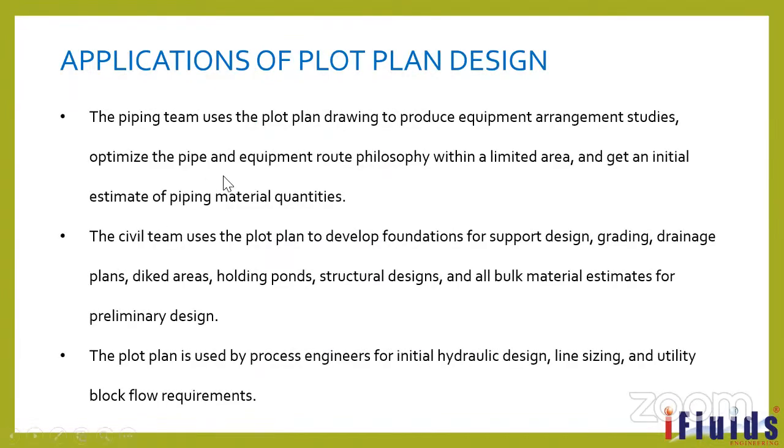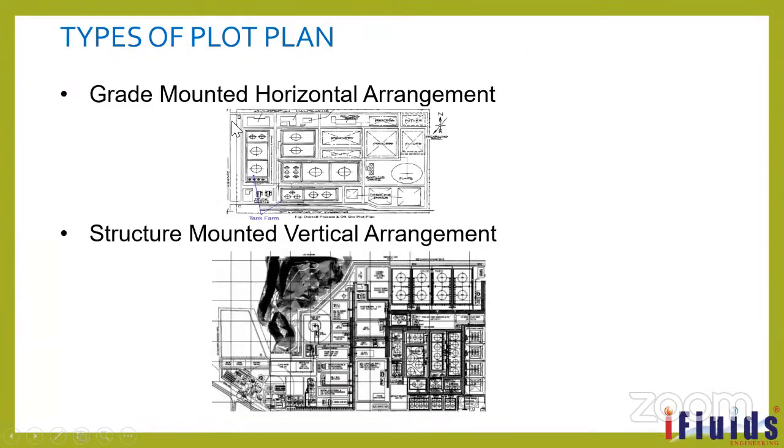What is the application of the plot plan? What will the team do with the help of the plot plan? The piping team can use the plot plan drawing to produce equipment arrangement studies, piping and equipment routing with limited area, and get an initial estimate of piping material. So the piping engineer, by seeing the plot plan itself,